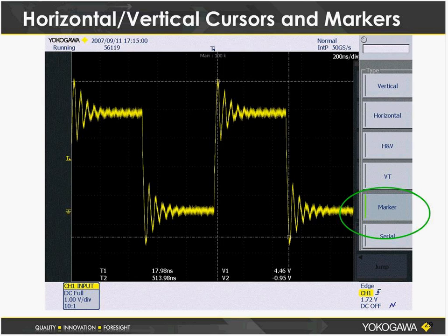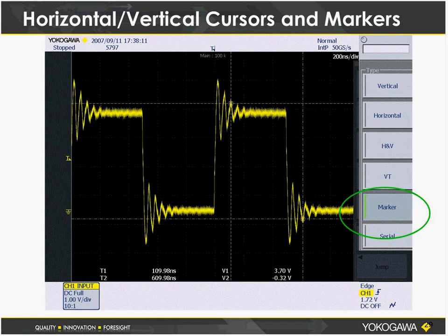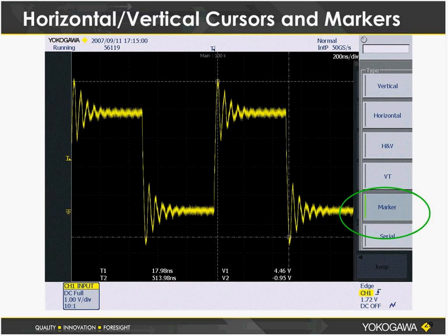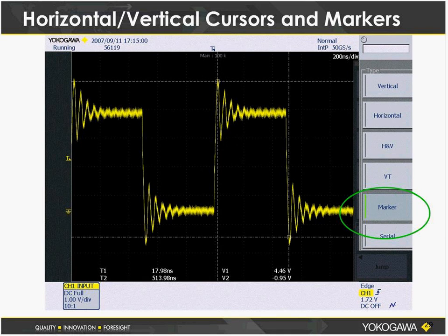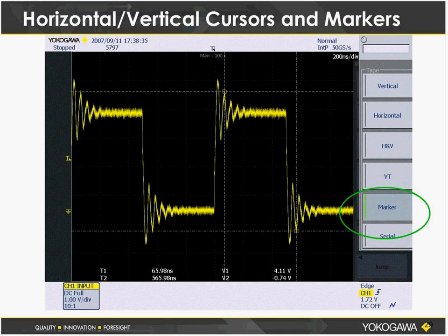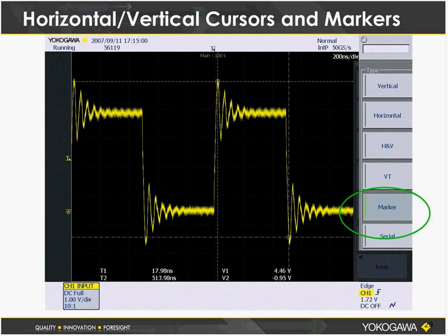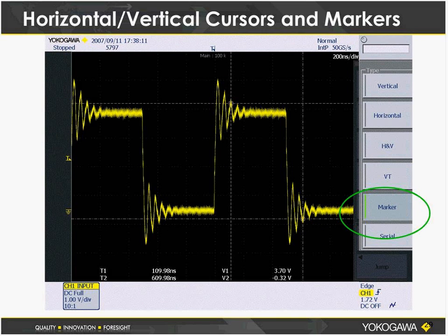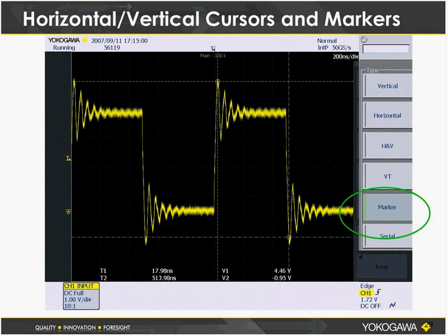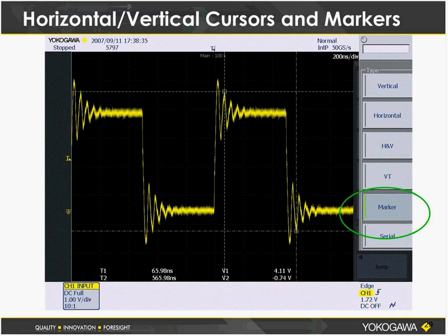So if you're looking for the most accurate measurement, the cursor measurement is actually not a good way to accomplish this. It will get you in the maybe 2 to 3% accuracy range, but it's not going to go down to the actual sample unless you zoom very, very closely, tightly into the signal to take your measurement. So keep that in mind. The cursor is just a starting point for automated measurement.